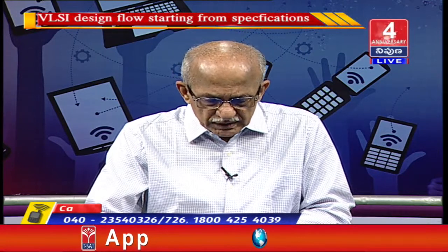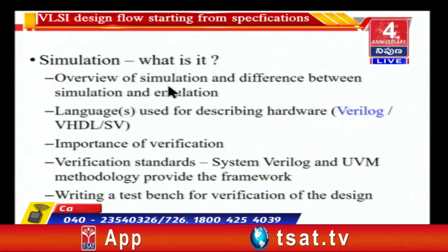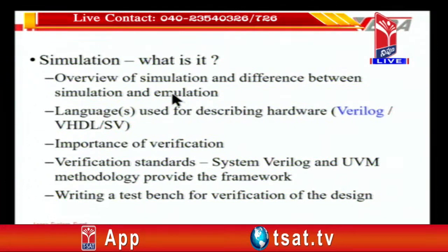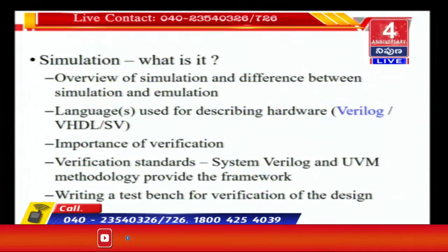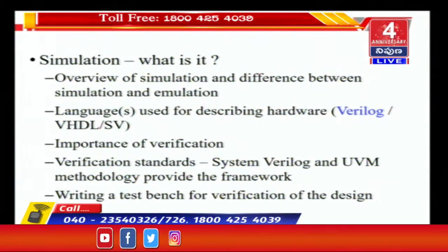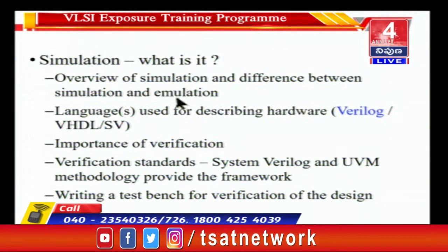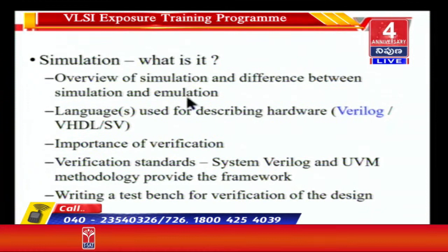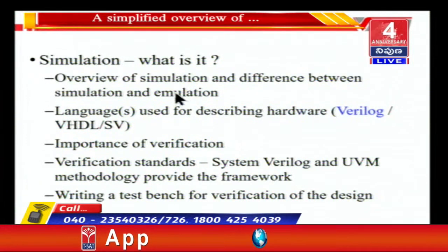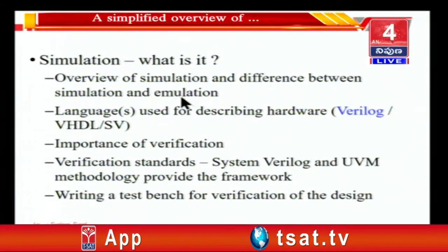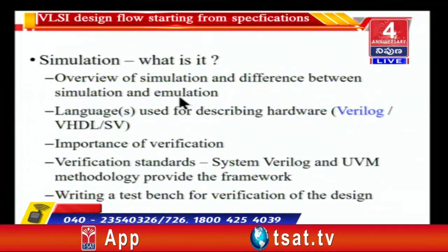If you want to verify the functionality of that particular microcontroller, you may have done so in simulation, but if you want to really check whether it's going to work correctly in hardware at very little extra cost, you would take this Verilog code for the microcontroller that you have written, synthesize it, target it to an FPGA and put that microcontroller design inside an FPGA. So now the FPGA works as a platform for verification of your design.